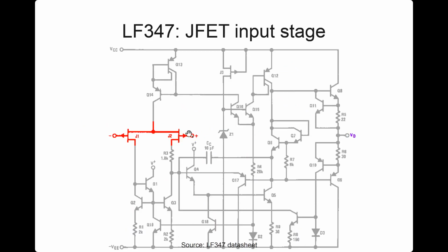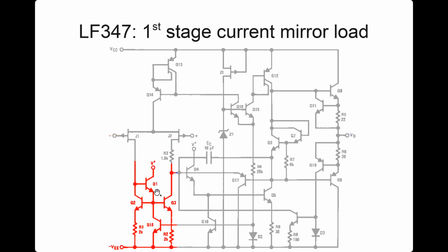Okay. So you can identify the input pair, and this is a current mirror, and I think you can recognize this also. Instead of the diode connecting this directly, it is through another transistor voltage follower. Again, it is to make sure that otherwise the base current is taken out of this, right? You have mirroring error. So to avoid these things, you have all of this stuff.